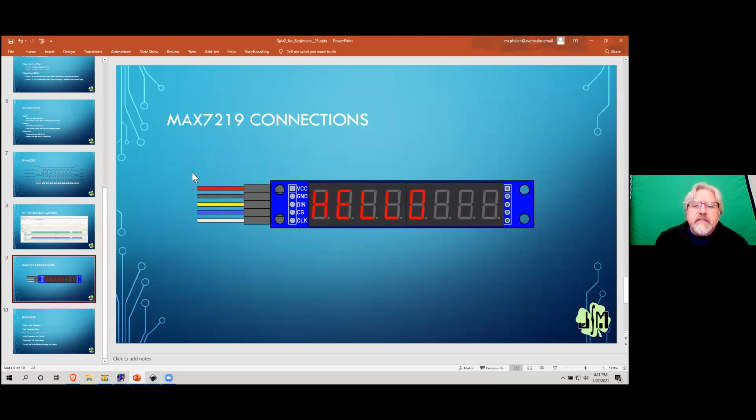Because it comes up from time to time, I did a diagram that shows the wire colors that I use. Again, just as with my code, I'm very specific how I do formatting because it helps me see the code and find problems when they exist. I choose specific wire colors as well. So red and black makes sense for power and ground. I use white for clock and yellow for data, just like I did with I2C.